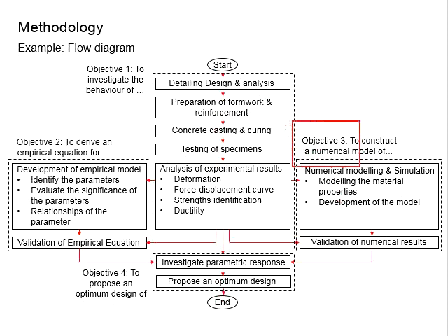And then maybe from the computer simulations, you will be able to observe what's happening within the specimen, especially in the context of the stress and strain. You might be able to identify the regions where high stress is concentrated, helping you to identify the weaknesses of the design, which may not be detected from the experiment.